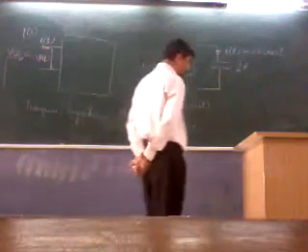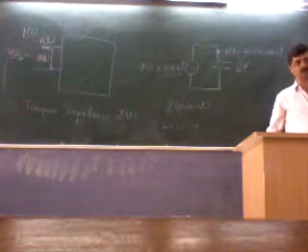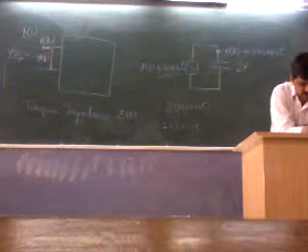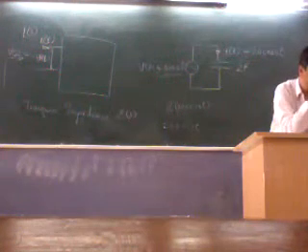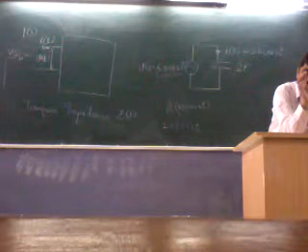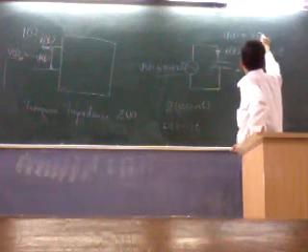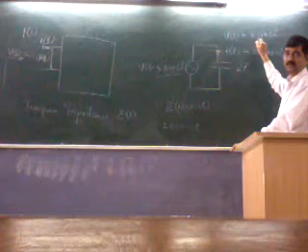Now the question is, the term impedance, which at one go describes the relative relationship between voltage across 2 points or across a device and current through the device. You getting me? Impedance is a term which describes the relationship between voltage across a device and current through the device by a single value. Are you getting me? It is some ratio. Now the problem before us is current is 20 cos 2t and Vt is 5 sin 2t. That is voltage across the capacitor, current through the capacitor.